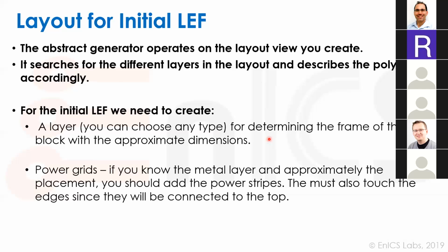One more thing is the directions that the macro could be rotated. It's also in the LEF. It could be, for example, mirrored across the y-axis, x-axis, or maybe rotated even 90 degrees. The 90 degrees rotation is already irrelevant in 60 nanometers, but beforehand it was possible too. This info is also in the LEF, and we should know it. It's called symmetry in the LEF. Yes, exactly. Otherwise the tool won't be able to rotate it for optimizations.